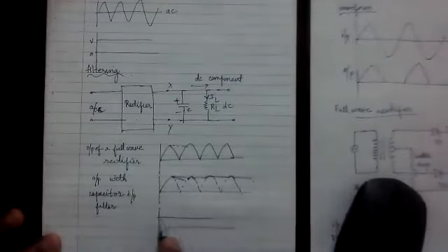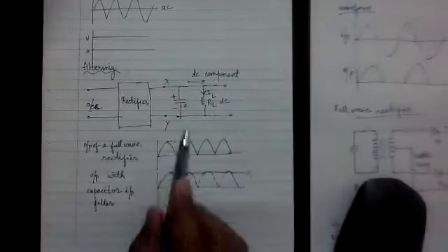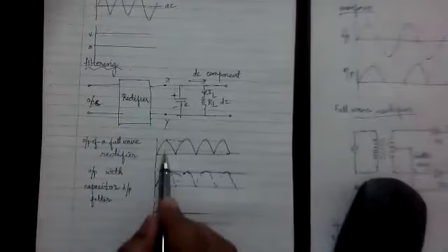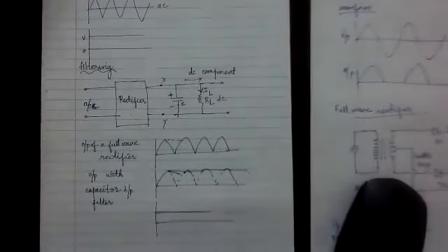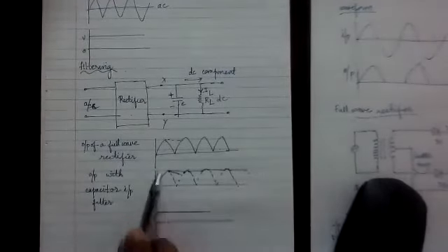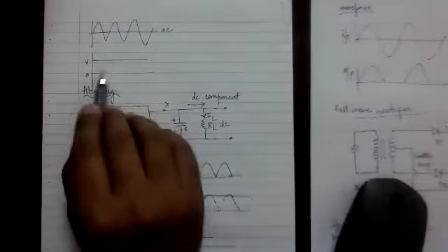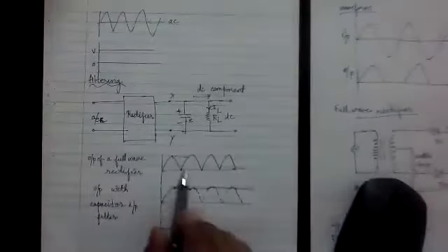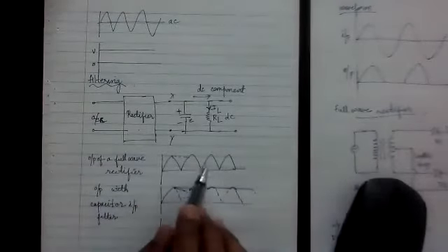What if there is a question like, sir, what if I don't give it directly, since this is a DC, the output of a full wave rectifier? So we can give it, right? You can give it, but your electronic device will get spoiled within a small period of time. Why? Because these ripples are not good for the electronic device. When I say DC, it should be a straight line, uniform. Electrons should flow uniformly, not like this, not like ripples. These are said to be the ripples, and this should not be given to the electronic device.